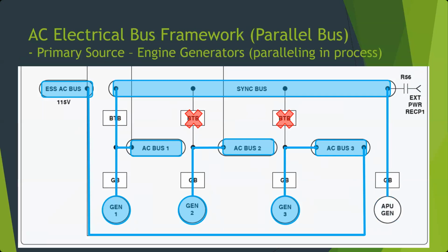When you have AC generators, when you start paralleling them with either the power card or with each other, when you get the frequencies close and you connect them together, they actually electrically lock into each other. Remember, an electrical current through a coil, which our generators have a bunch of, creates a force.